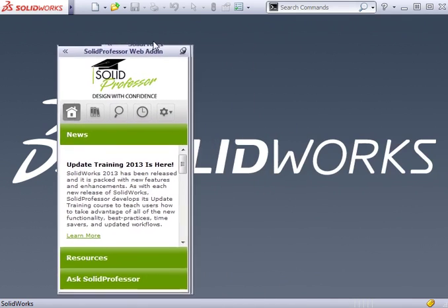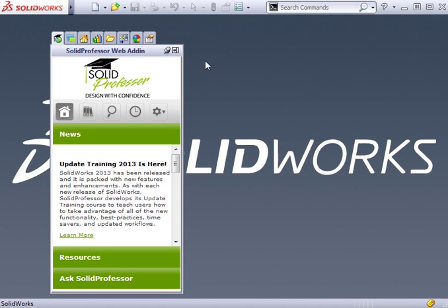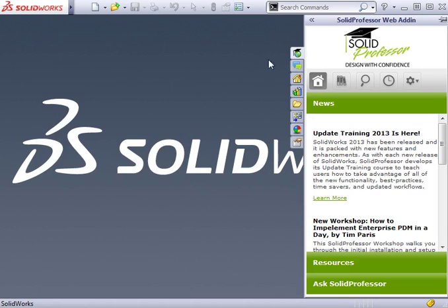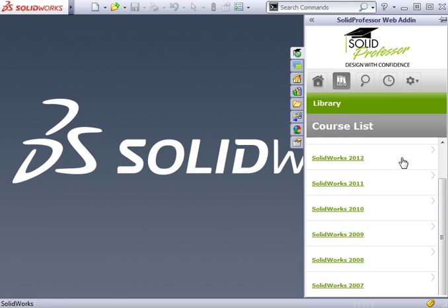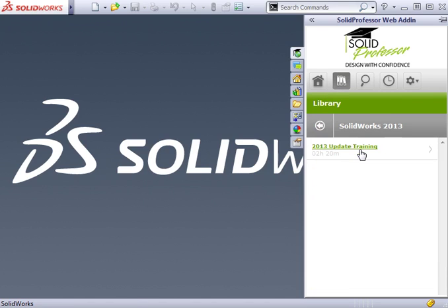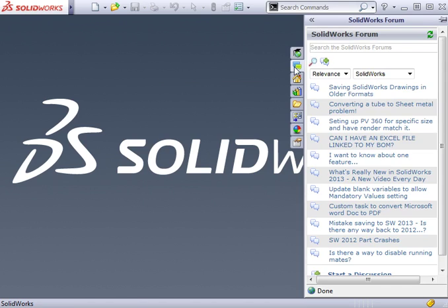By default, it displays the icons with a text description. To turn off the text descriptions, right-click on top of the Command Manager and uncheck Use Large Buttons with Text. For the duration of this instruction, the text will be turned off on all icons to allow for easier display of all the commands available.